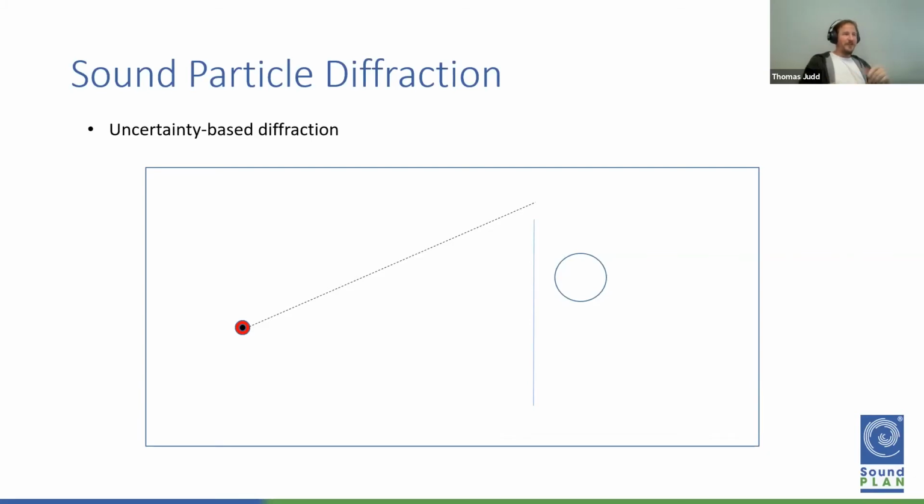And the way it works is, say I've got my sound particle that goes whizzing past my little corner there. What I do is I've got my screening wall here, and I imagine I extend that screening wall with something called a virtual wall, which is acoustically transparent, and then I can note the point that my particle hits that virtual wall, and from that strike point I can get the distance between any solid objects I have close by. From these distances, these bypass distances as we call them, I can get an effective slit width, and of course a slit is integral to the idea of diffraction.